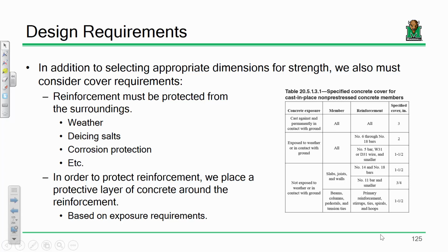When steel rusts, I mean, obviously it gets brown, it gets gritty, but what else does it do? It breaks apart. It corrodes. But when metal rusts, it expands. The volume actually increases. Now, think about it like this. I have a beam, I have rebar embedded in the beam, the rebar is corroding. Rebar expands. What happens then? We start cracking the beam, and we can start having some very serious problems, okay?